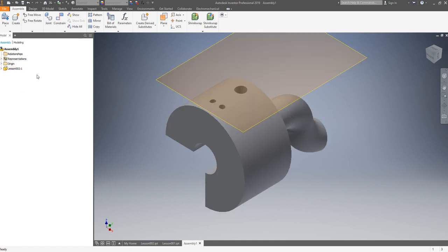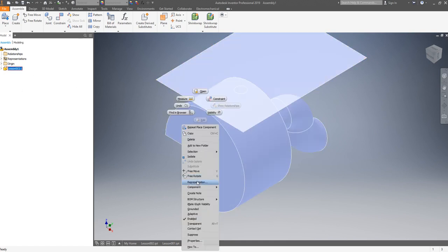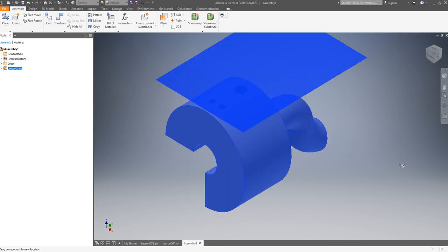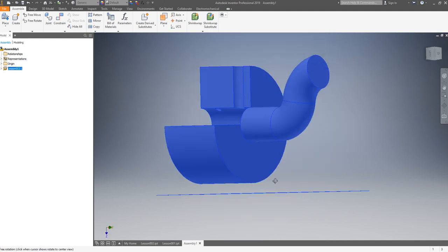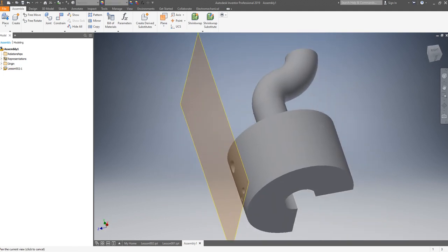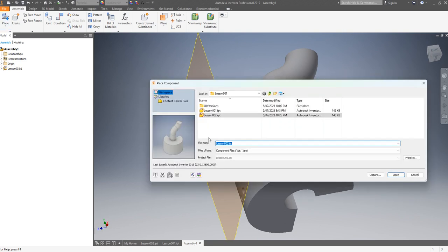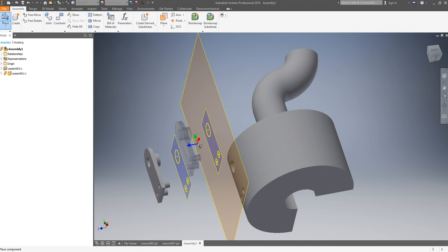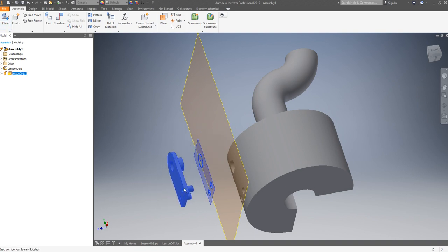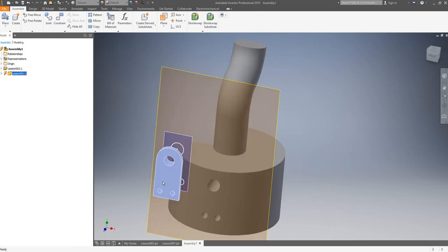If we want to stabilize that, just click that, right click, and put this one grounded. So that means I can't move it. You click that, you can't move it. Now let's put another part. Place this part I want to put in. I click OK. The part is there, and I haven't grounded, so I click that. I can move it. That means it has a lot of degrees of freedom. So in order to put this part attach onto that, you will limit the freedom, right?